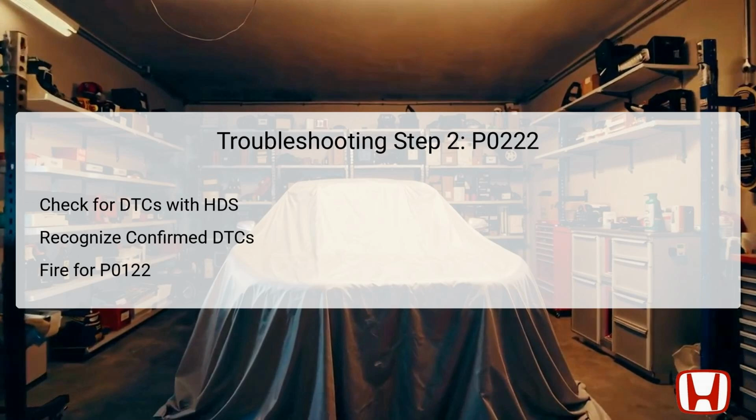Conversely, if only DTC P0222 is showing, you will then move on to step 3 to investigate potential shorting issues within the wiring. This distinction is crucial because it helps narrow down the source of the problem, whether it is related to one specific sensor or both.